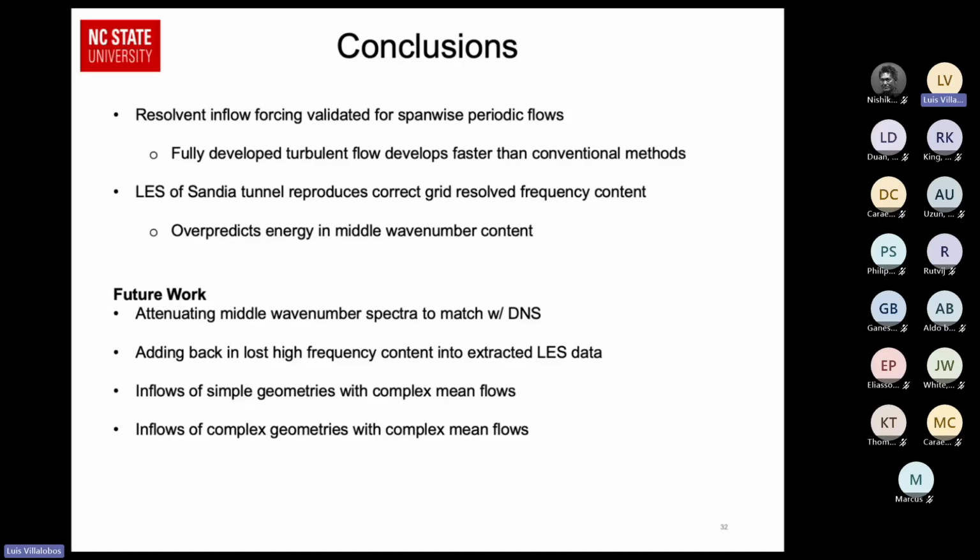Another avenue of work that we want to look into is adding back in the high frequency content into the LES data. So as you saw, we were cutting off those highest frequencies, and those might impact transition, for example, for second mode disturbances, but we're not entirely sure. That's still an active area that we really want to look into. Perhaps we could just use the LES data that we already have as an inflow boundary condition for a transition DNS.